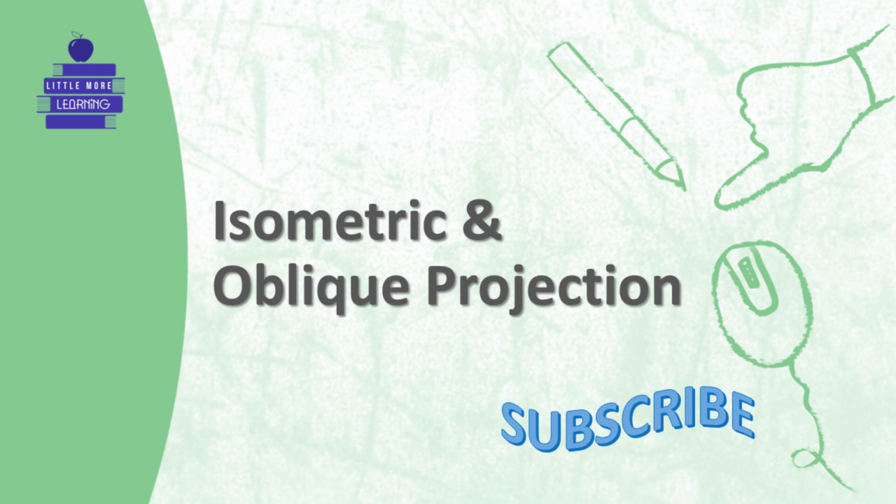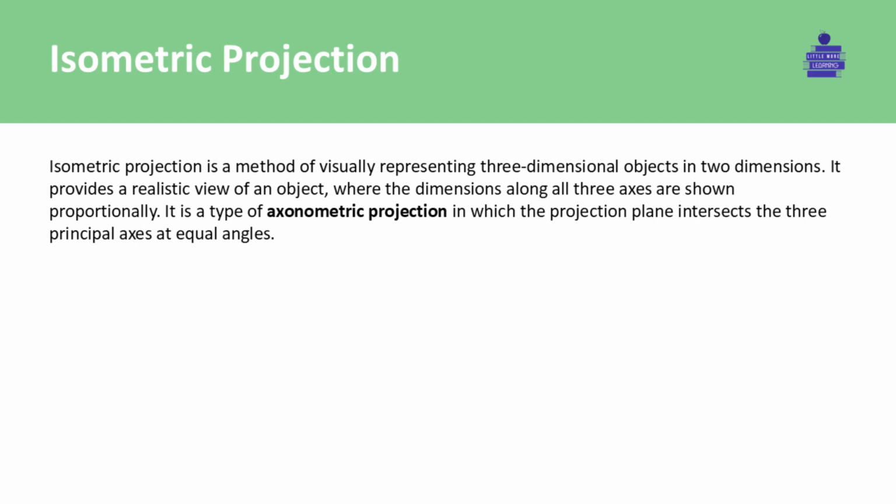Welcome, everyone. Today we're going to dive into a fascinating topic in technical drawing: isometric and oblique projection. Think of isometric projection as a way to show a three-dimensional object on our two-dimensional paper or screen, but with a special twist. What makes it special? Well, it allows us to see all three dimensions, length, width, and height, in a proportional way that looks realistic to our eyes. Imagine you're looking at a cube from a corner. That's essentially what isometric projection gives us.